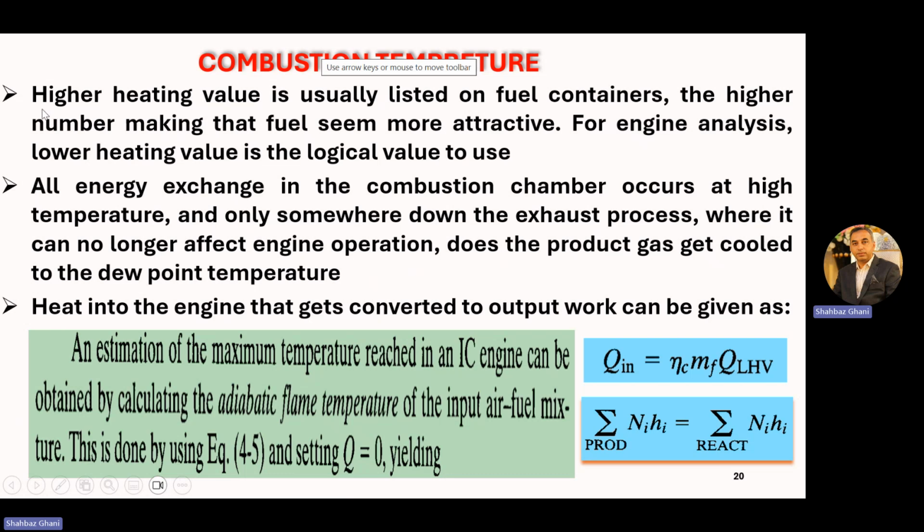Generally, we find that the higher heating value is listed on the fuel container, the higher number making that fuel seem more attractive. For engine analysis, the lower heating value is the logical value to use. On the container we have a higher heating value that seems more attractive, but for analysis of an engine, we must take the lower heating value. That is a logical way to use it.